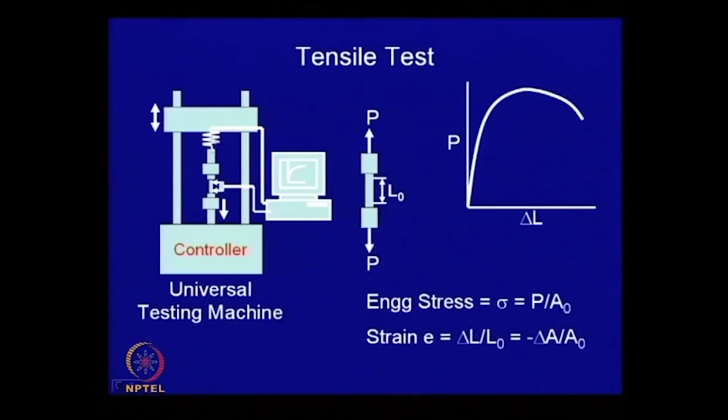Similarly, the load cell also gives volt signal, which also can be recorded on the computer disk. And the main controller is over here. This controller moves an actuator which can move this pull rod in a user defined way. In a tensile test, we will be pulling it along this direction.